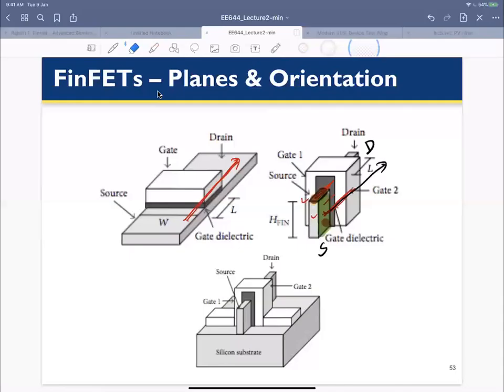That's the reason when you do the design. So basically, if you have done the digital design course, you know that you size the transistor based on the mobility, right? Since the mobilities are equal, the sizes of both NMOS and PMOS transistors will be equal.